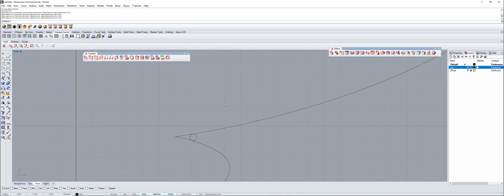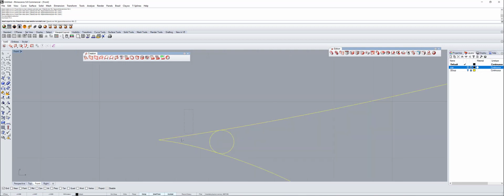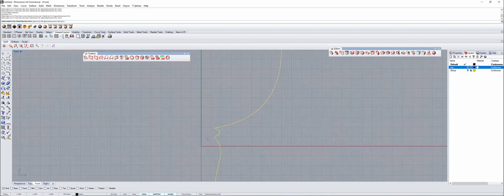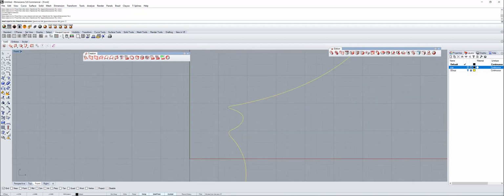And I'm gonna do the same thing over here. So I click outside, without touching any drawing or surface or something that I can have there. I'm gonna click over here, and I select everything, and I'm gonna press enter because I already used trim, and I'm gonna do it like this, and now we got those round shapes, not those mechanical shapes that are like squares.